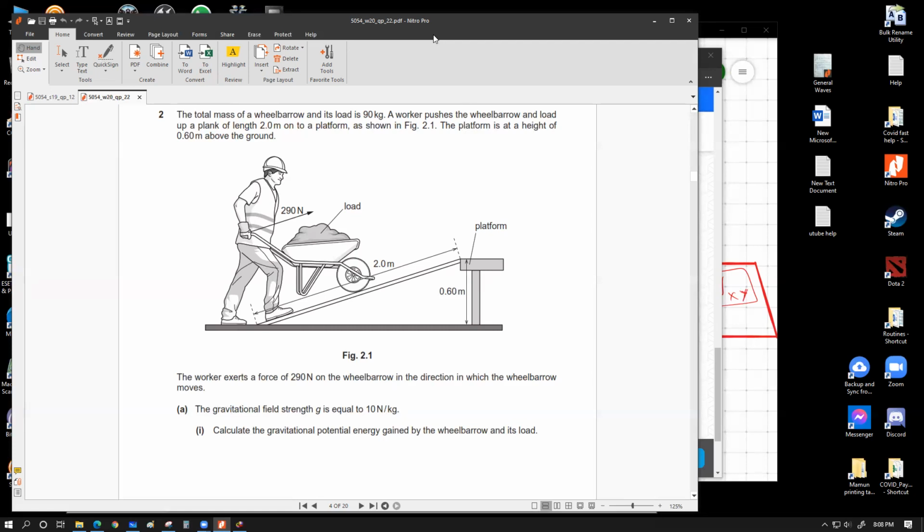So all the electrical energy that you are actually spending to achieve the heating process is not practically getting stored or remaining within the water that you are heating up. Significant other substances are absorbing heat energy, and you're also losing some heat to the surroundings because of four processes here: conduction, convection, radiation, and also evaporation out of the open surface of the water. So all of these losses ultimately cause the efficiency of the whole thing to be much less than 100%.